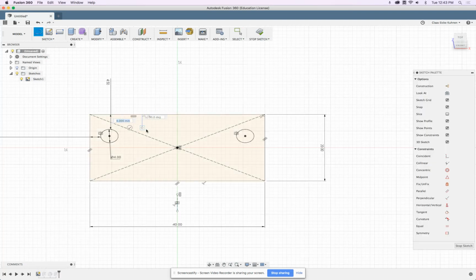I just make myself 2 lines there. Very good. So we set this should be 7.5 and these 2 points dimension should be 20. I have here perpendicular constraints, which I hate because I don't know perpendicular to what. Since everything is aligned horizontally, vertically, here I will set this to horizontal vertical constraints.